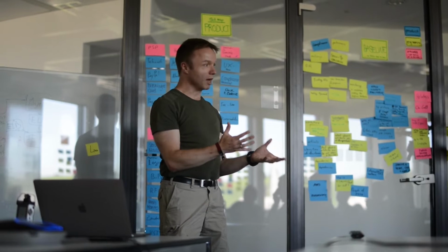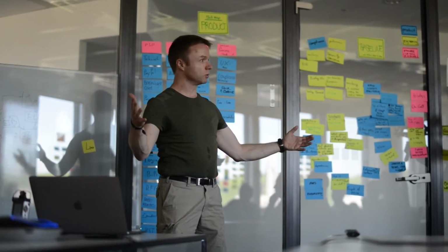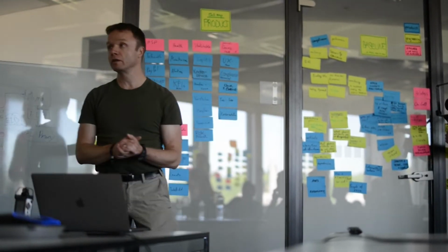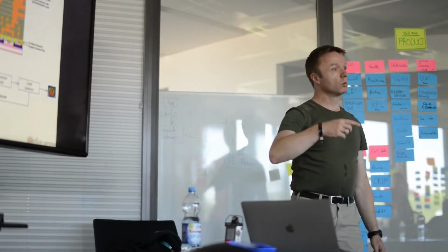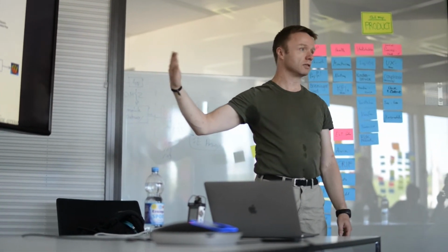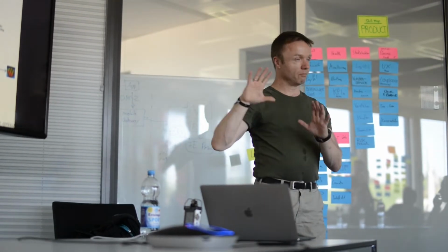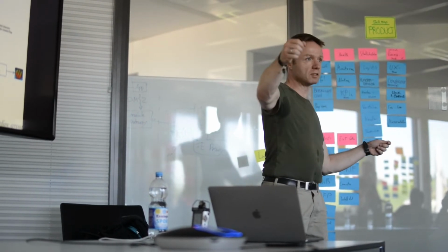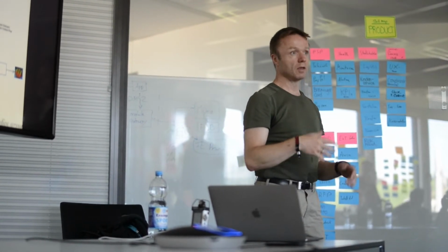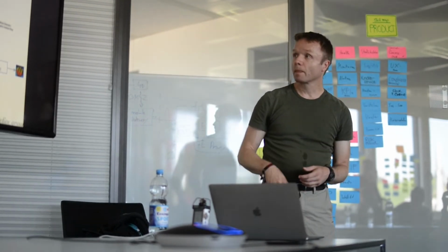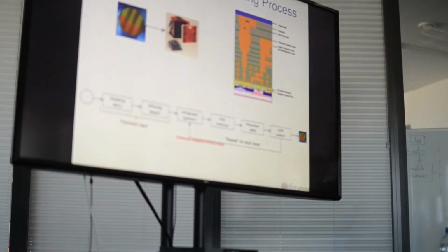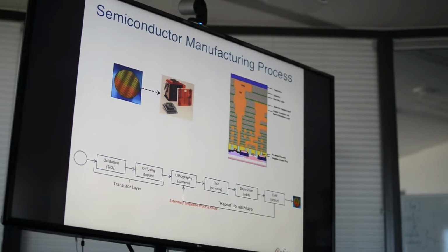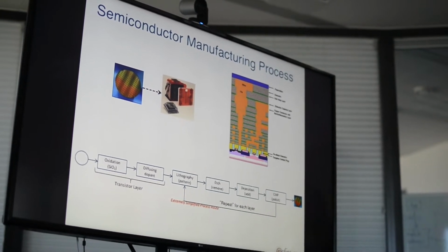Instead, a modern microprocessor goes through about 1,000 manufacturing steps that are spread out over several weeks. And of course, a modern semiconductor has many layers, so it goes through the same kinds of machines many times in a given factory. These machines are very, very expensive, and that means that a factory can't just buy enough machines and line them up in an assembly line, and also they break down all the time. So there are various complicated problems that have to do with finding out what is the best machine to put your wafer through next, when it comes out of the previous machine. Problem sort of clear?